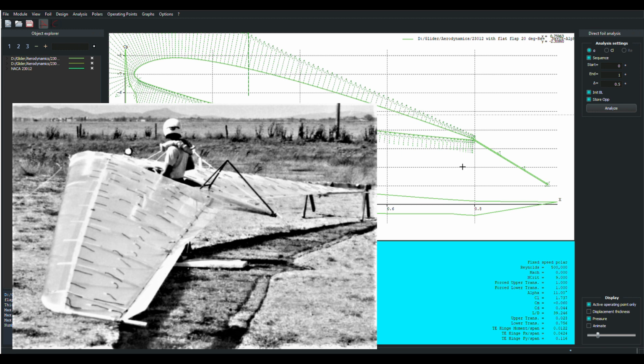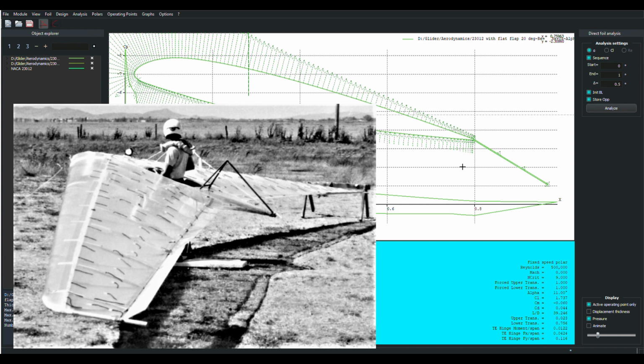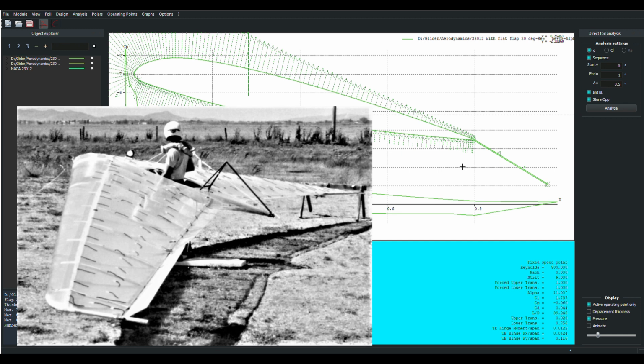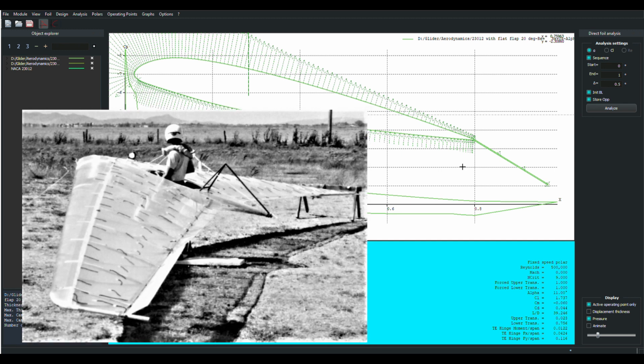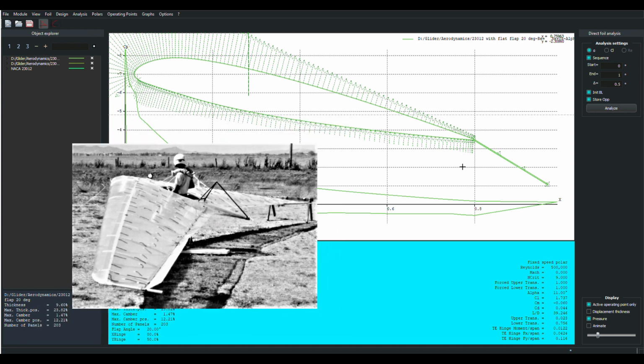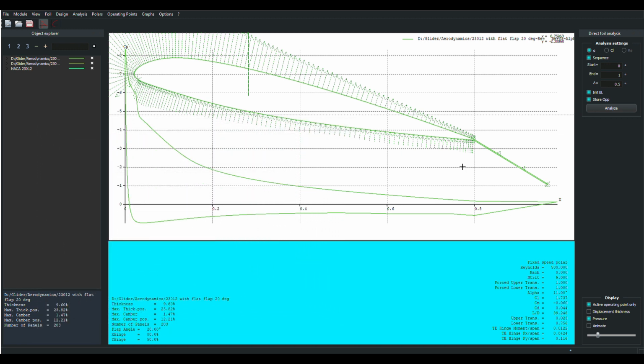The reason that they were 3/4 of an inch thick at the front was for structural considerations, and it also matched up with the trailing edge of the ribs, which you'll see in another segment of this video. You'll see that the ribs have a certain minimum height at the trailing edge because of how they were made, and I just made the elevon match that, so I would match up with the outer surfaces of the airfoil at that point. So I ended up with a triangular shaped, essentially flat plate elevon, and they were a fantastic control system.